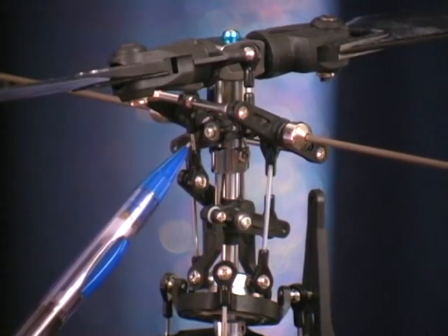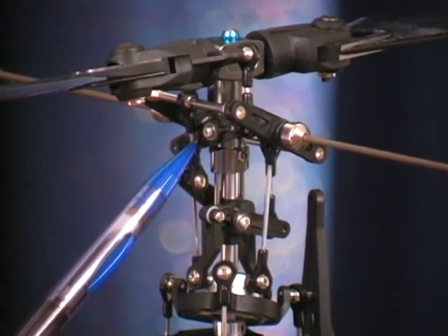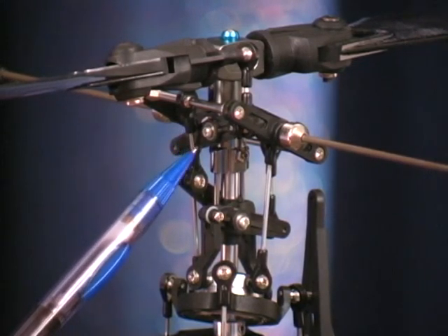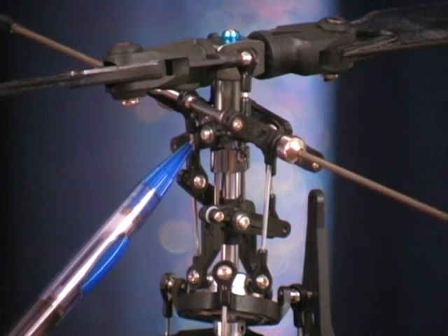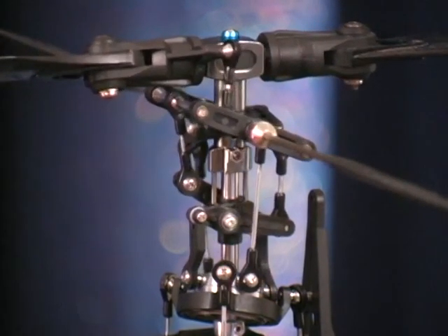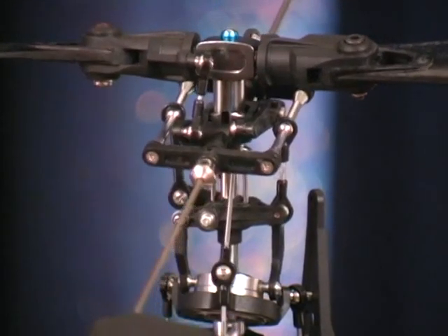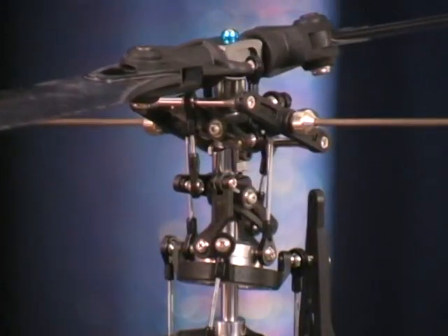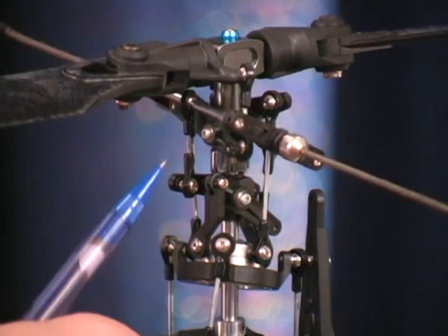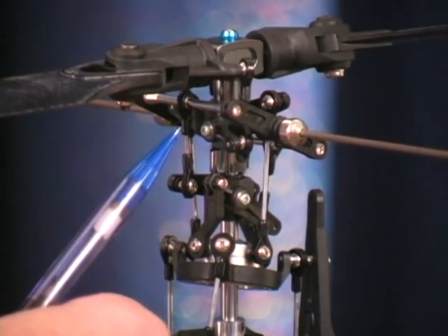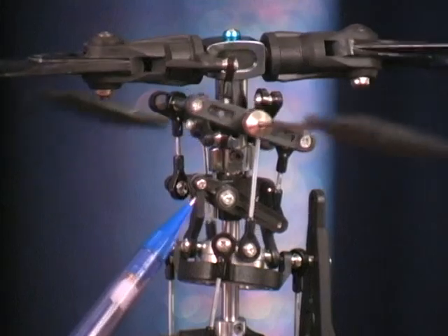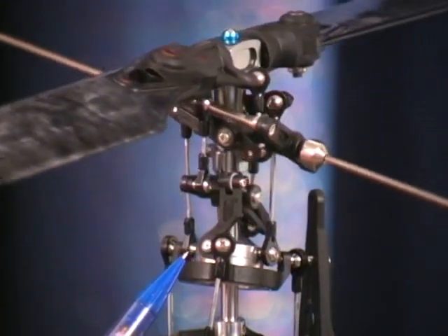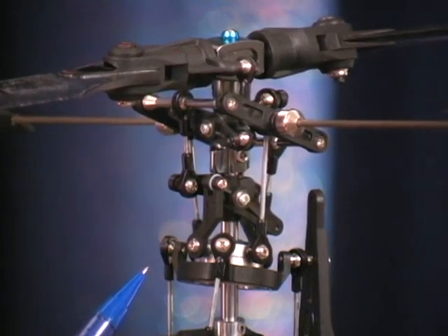I've also ground with a little sanding drum in this mixer arm area. I've ground off the little reinforcement rib because this push rod lays right in there in the mixer area. And let's go to full high stick. Same thing, I've got some binding here. But everything else looks pretty good.